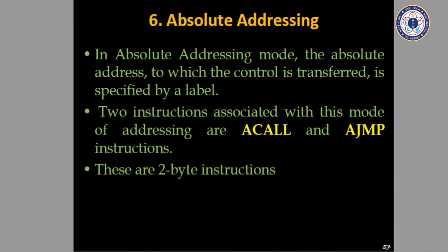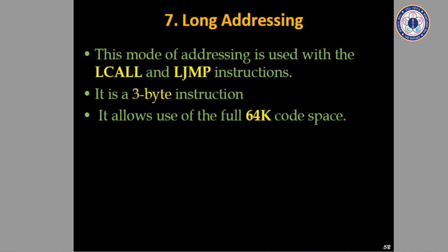And now the next one is long call. Long call means we can access the full 64 kilobytes of locations. That means long call or long jump. It is a 3-byte instruction. We can access anywhere within the 64 kilobytes of location.